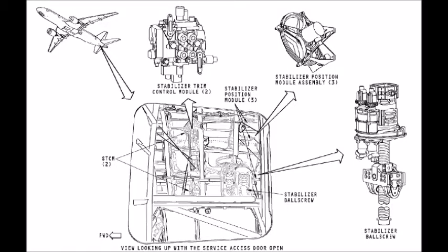The horizontal stabilizer supplies a long-term correction of the pitch attitude of the airplane. This movement is around the lateral axis of the airplane. Stabilizer control: the elevator offload function automatically sets the position of the stabilizer during manual flight or in auto flight. In this mode, the PFCs monitor elevator deflection and transfer pitch changes to the stabilizer. Once the stabilizer goes to its commanded position, the elevator moves to neutral.